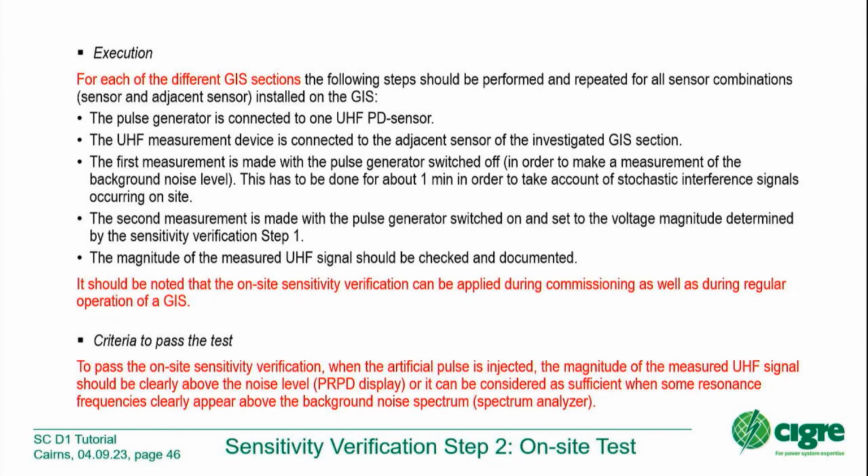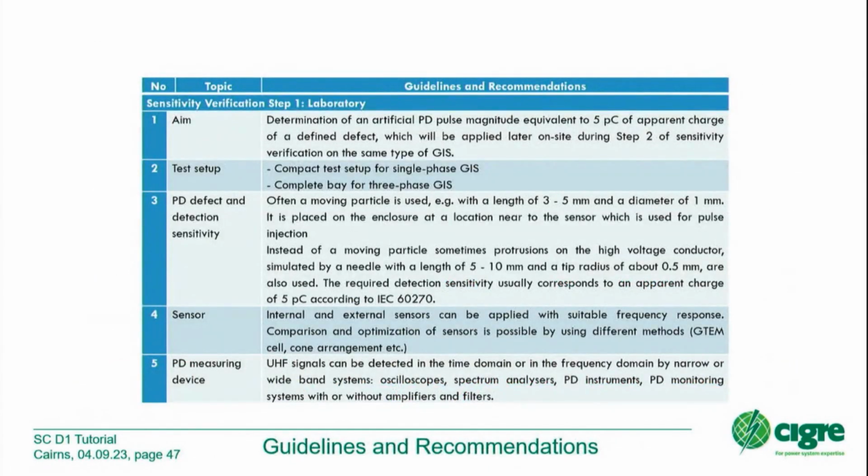And the criterion to pass the on-site sensitivity verification is that the artificial pulse injected and the adjacent UHF sensor should clearly show an amplitude above the noise level. That's important. And last but not least, the technical brochure finishes with this kind of tables.